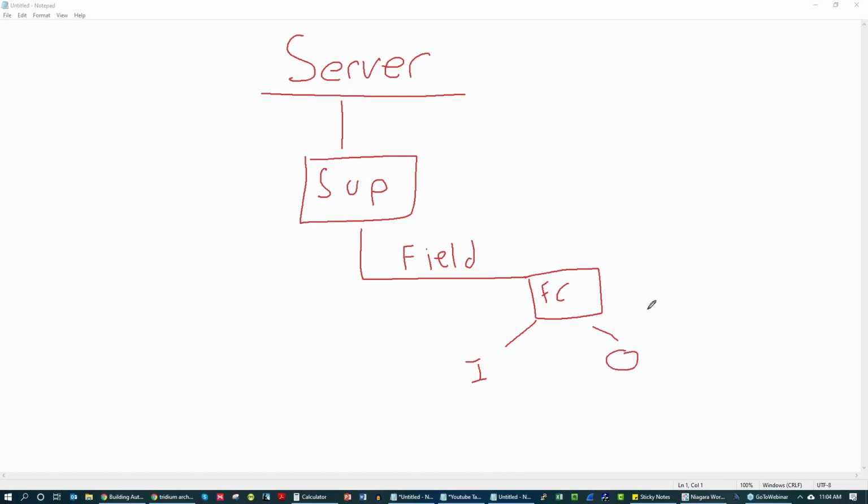So as we're looking for a control system or a building automation system, and our customer, or we being the customer, are looking into this, we have to decide what we're trying to work with. Are we trying to work with field controllers? Are we trying to work with pulling in existing field controllers, in which case we're using a supervisory device? Or are we pulling in an existing system, in which case we're using a server?